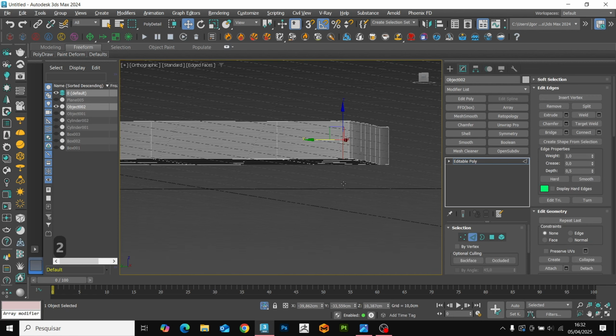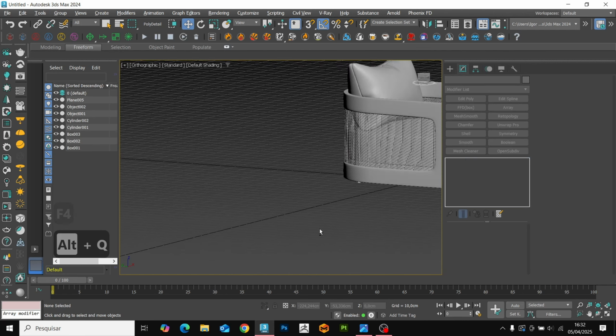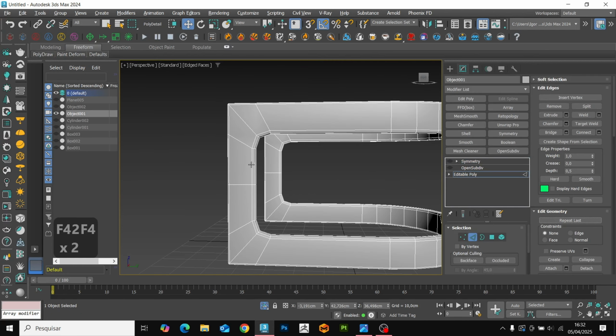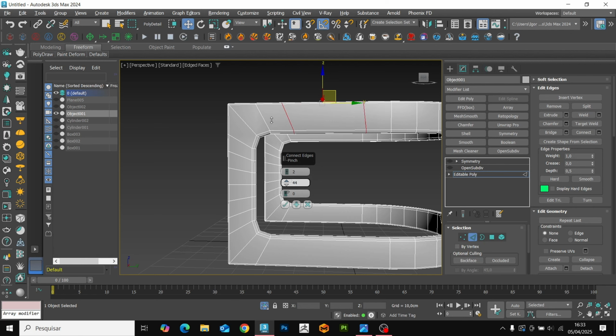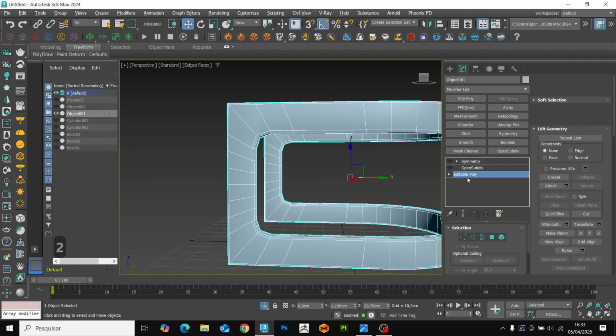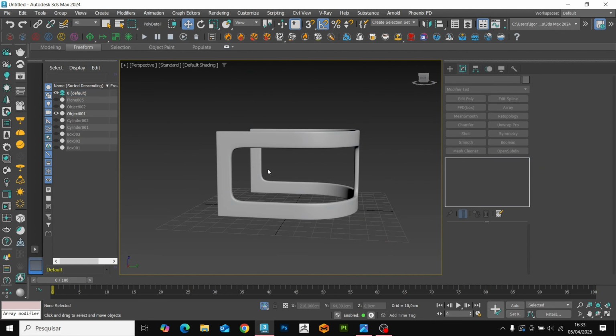Once that is done, we will add some support loops and a modifier to smooth the shape. Here, returning to the base of the chair, I will add some support loops to keep the curve a little tighter. So let's add 2 support loops all the way around the object, near the parts where the edges change direction. And so we have the solid and firm base of our model.